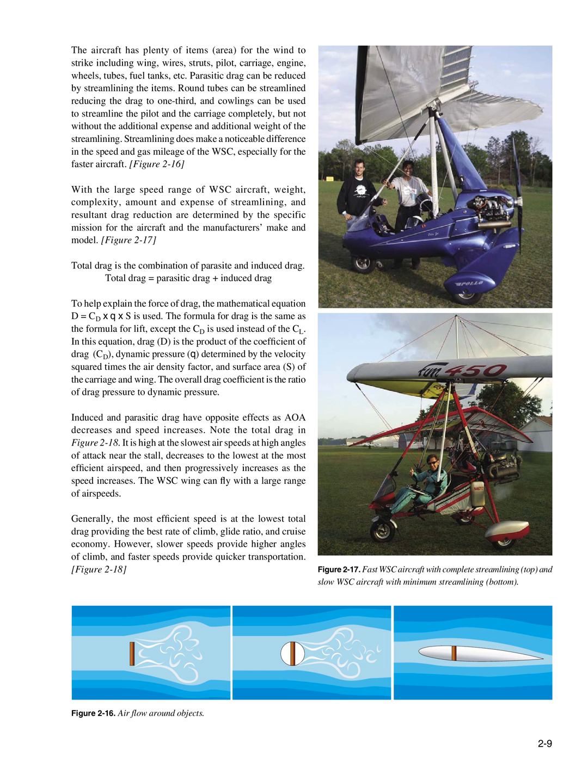Induced and parasitic drag have opposite effects as AOA decreases and speed increases. Note the total drag in Figure 218. It is high at the slowest airspeeds at high angles of attack near the stall, decreases to the lowest at the most efficient airspeed, and then progressively increases as the speed increases.